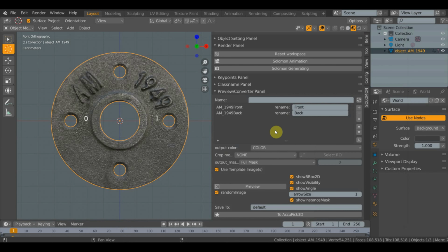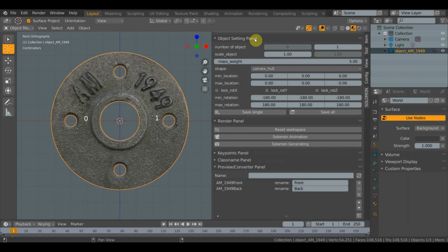For every simulation I was considering to generate one single object, but now I need to assign the real quantity of objects I will have the moment when I will conduct the picking process. In this case, 25 is the maximum number of objects I will have to pick from the bin. Therefore, the range of objects I will add to each image will be randomly selected from 1 to 25 items. There is not a limit for the number of objects you want to consider for your case. To have a more realistic scenario, it's better to consider the real weight of the object. Don't forget to save any modification applied in Object Setting panel.